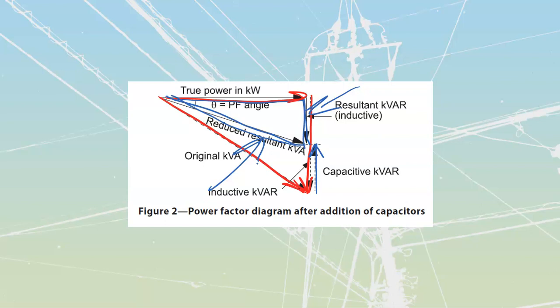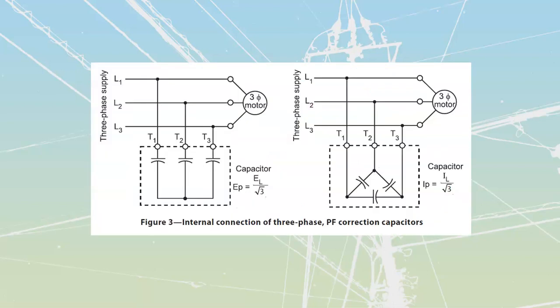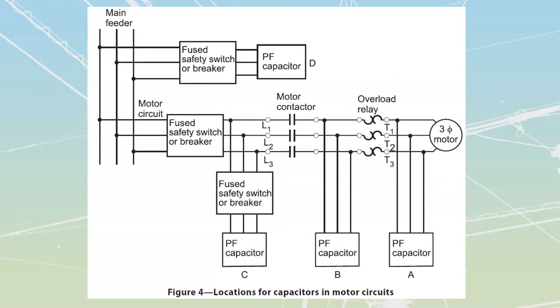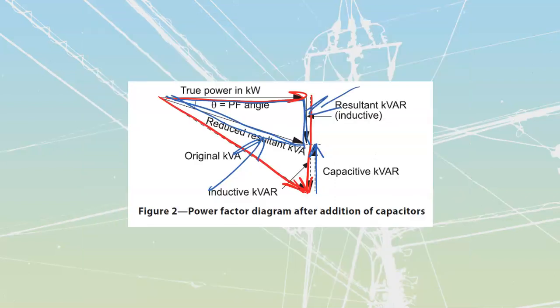Three basic methods that we're going to use for correcting power factor. Those are going to be individual capacitor units, where we take individual ones and connect them across a load. Stick an individual cap size to the loads, in kvars, at each individual load. This is going to take time and it's expensive because you're going to have to go to each load, sort out how much capacity you need to correct, and then connect it on at each one.